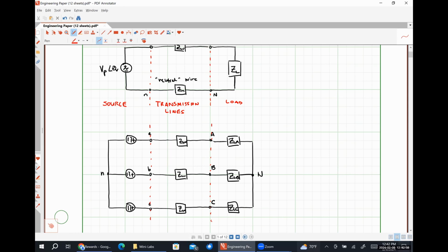If you were talking about delivering power to an induction motor specifically, and even then it wouldn't necessarily be efficiency. As we'll see in a couple of days, the average power and the instantaneous power delivered in a balanced three-phase system is actually constant. So if we connect a motor to a balanced three-phase system, it will have a constant torque, which is a pretty huge deal, because effectively that means that since the power hitting the motor isn't surging, it's not going to vibrate.